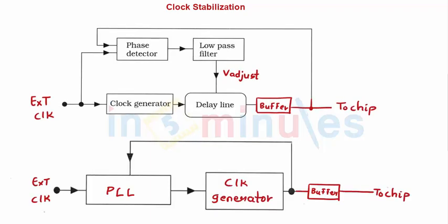Don't get intimidated by what you see on the screen. It's a very straightforward block diagram where I have an external clock which is present here. The external clock is given to my clock generator circuit. We saw in the previous clip, this was my external clock and we passed it through a chain of inverters or through a latch. We have already done this in the previous clip, right? And here was our capacitor and we generated phi and phi bar internally for internal operation.